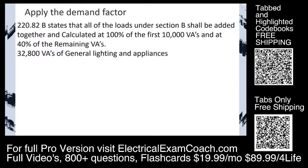Now that we've learned to take our 3 VAs per square foot and our 4,500, and then to take the nameplate of all the appliances, let's learn how to apply the demand factor to this portion of the calculation. It's super simple. You just total all that up and then apply 1 general demand factor.